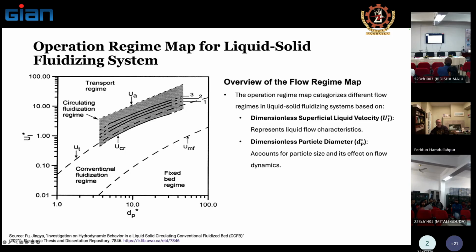Then in this corridor, you run a conventional fluidization regime, okay? The bed is suspended and it's in the form that I showed you before. Of course, needless to say, in this case, we're not talking about bubbles. It's all incipient, okay? And it's all uniform, but nevertheless, it's a conventional fluid bed.